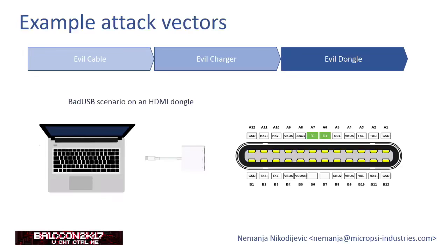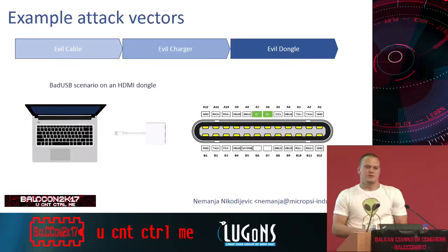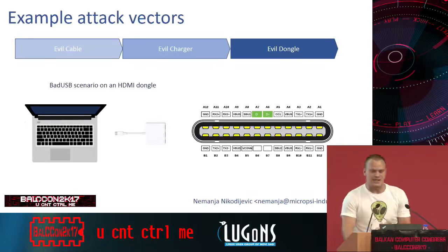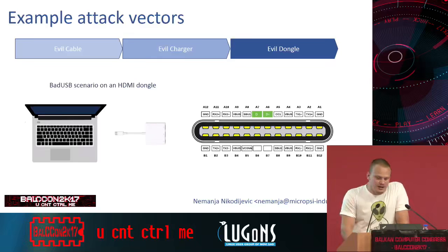So when you connect it to a computer like mine that doesn't have a USB Type-C input, you can basically see that it shows up as a billboard device. And apparently, I was lucky. The one that I ordered from Amazon just came with firmware that was just an unaltered example from the chip manufacturer. So basically, I just went to the chip manufacturer's website, downloaded the software development kit, and I had the complete source code that was running on the dongle.